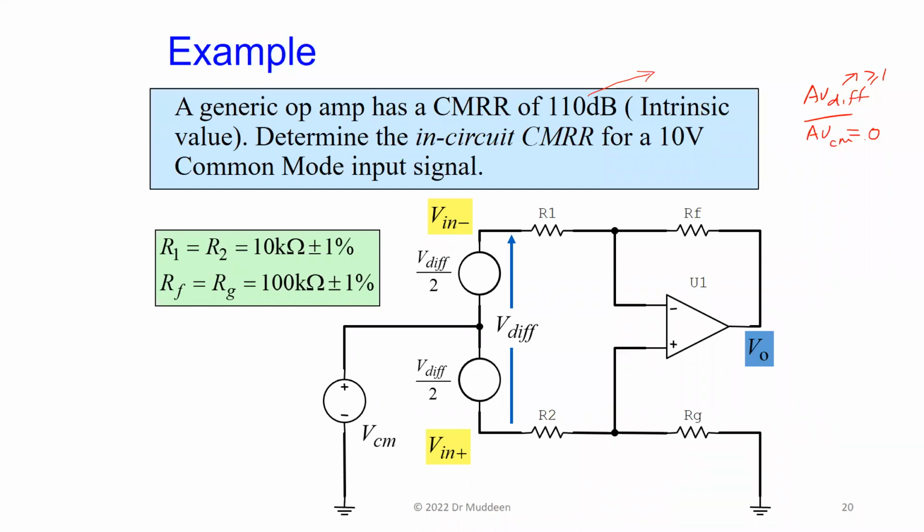So let's see what happens if I take this nice expensive op-amp and make a differential amplifier using 1% resistors. 1% are pretty good resistors. You get them in stores right now, and they are about the most accurate of those small little resistors with the color bands that you can get. Remember how we get the gain to be just RF over R1: we usually match these two resistors. So nominally this is supposed to be 10K here, and this now is supposed to be 100K.